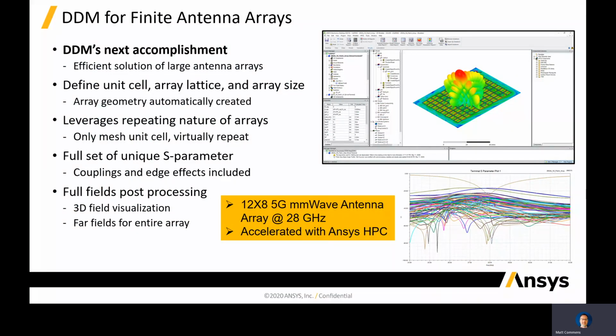Now, this provides us a full set of unique S-parameters and coupling parameters for all the different antenna elements and all their couplings to the other elements, and provides us full field post-processing, allowing us to, for example, do 3D field visualization or far fields of the entire array. Again, same theme, no compromise to the accuracy.